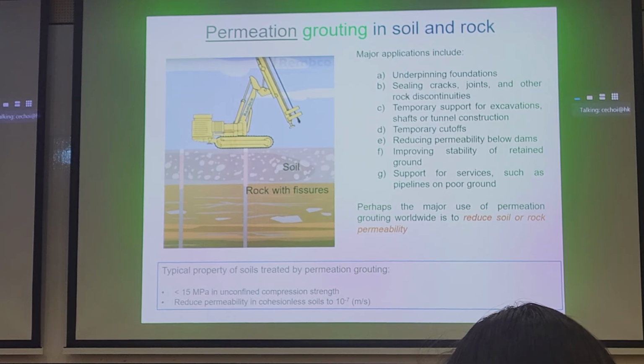The second part of the question was, I think, if you have settlement, how to deal with existing pipes in the ground. Well, one way is just you monitor the pipes, right? This is a passive approach, you do nothing. You put settlement markers on the joints of a pipe. So the pipes fit together like this, right? If you put a settlement marker on the joint, you can monitor it with time.